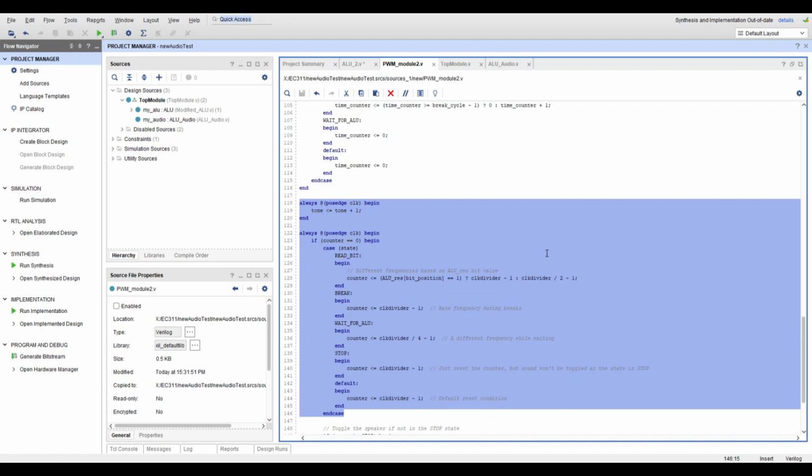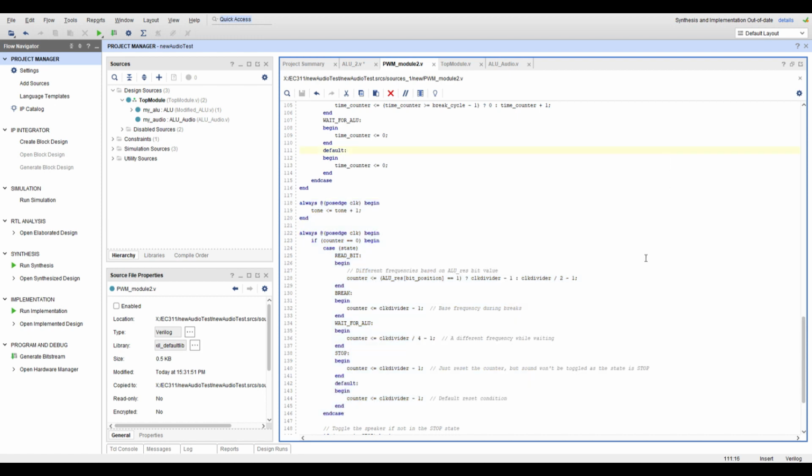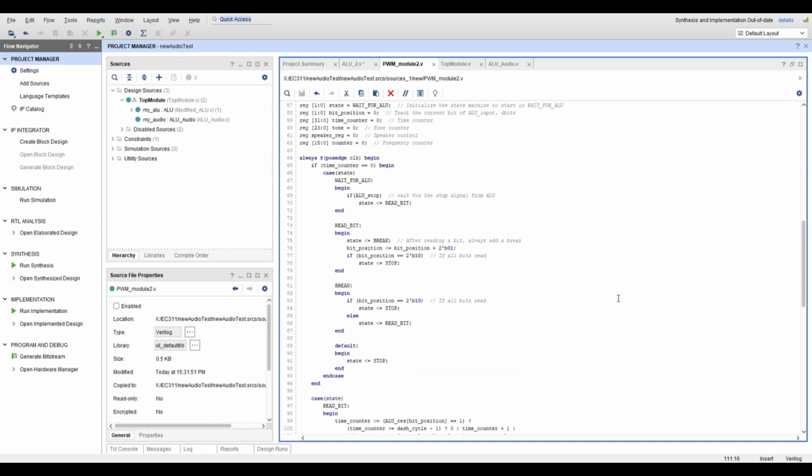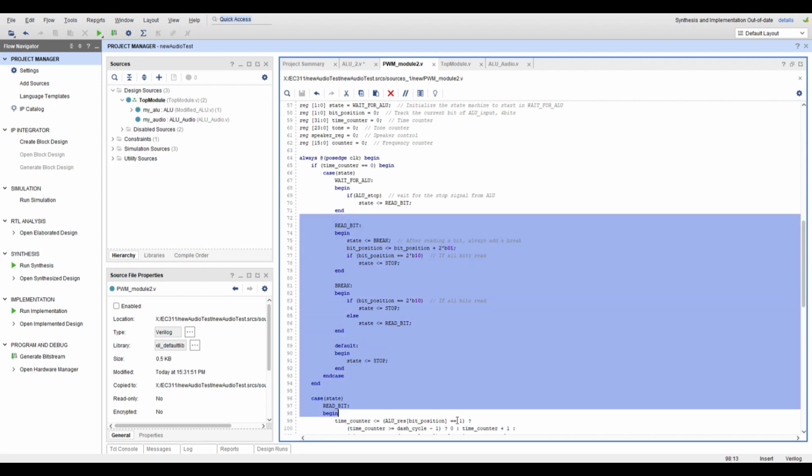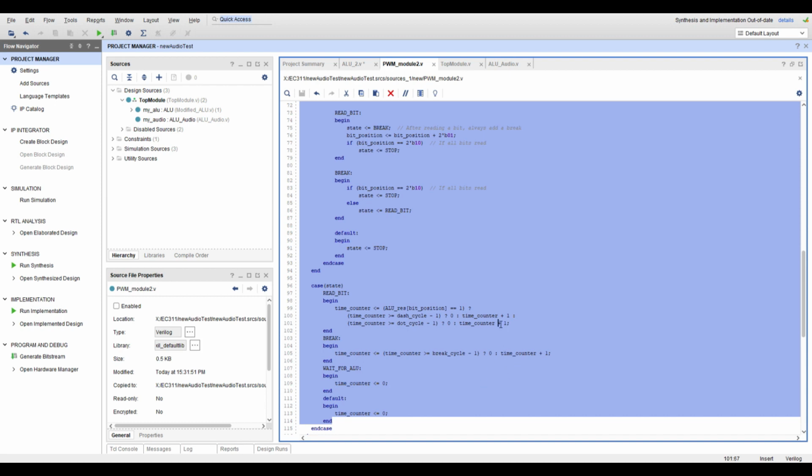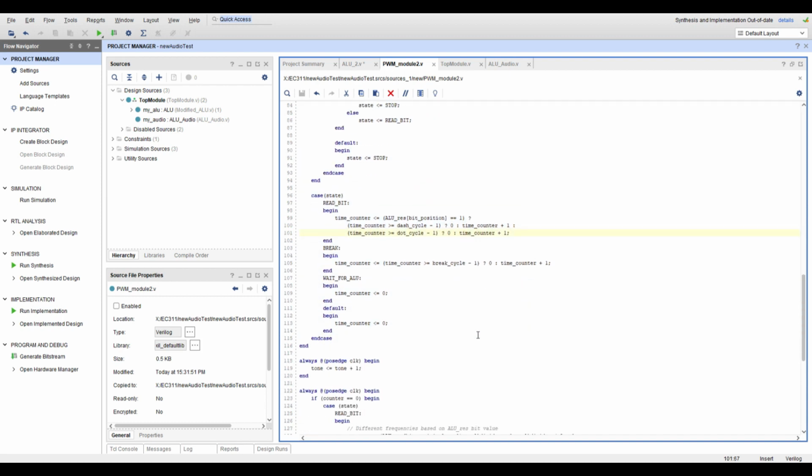Okay, in our Lab 3, we use a speaker with a PWM signal as our output. For each clock cycle, the PWM wave is produced using a counter. The duty cycle of the PWM, which indicates the resulting amplitude, is determined by the percentage of ones in the final signal. Our initial goal was to generate Morse code-like sound for sequential binary numbers. However, we encountered some issues with this initial approach. In our initial approach, we integrated a state machine to enable the speaker to interpret zeros and ones over varying time intervals. During the phase, we realized that representing each bit with a distinct frequency might be more efficient.